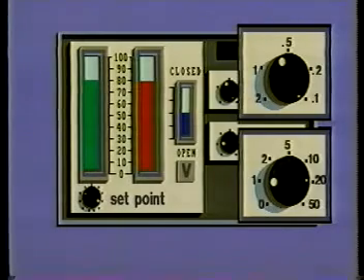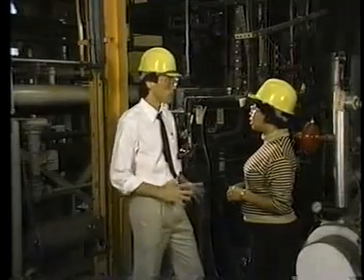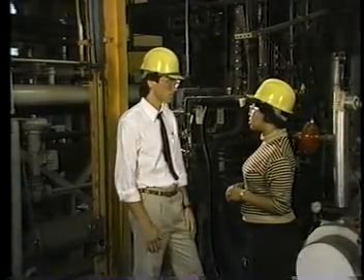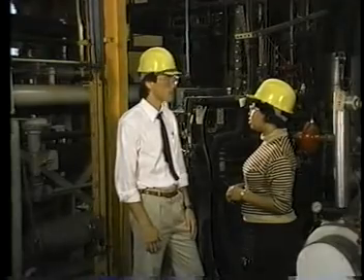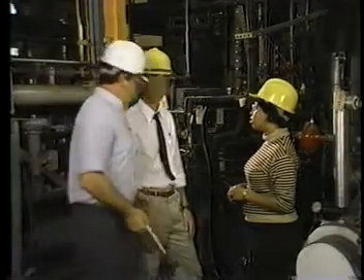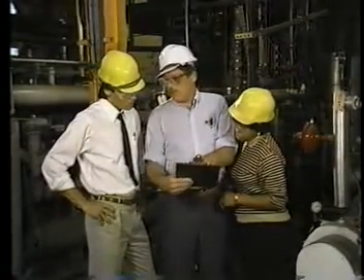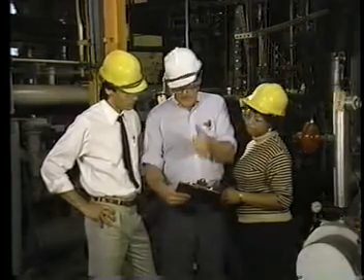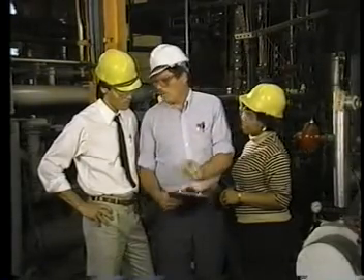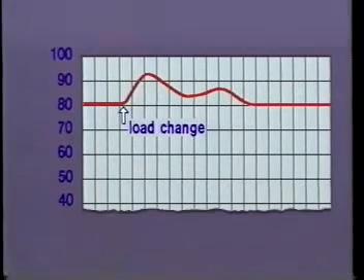Higher gain and faster integral values caused the process to become unstable. Lower values were too slow for good performance. The company was pleased that the new two-mode controller solved the problem of load changes. But the production foreman, the person responsible for product quality, pointed out that every time the second machine was started or stopped, there was a large temporary deviation, during which about 50 bottles were off standard and had to be thrown out. The sudden load changes were causing the trouble. Slower and smaller load changes caused no such difficulty.